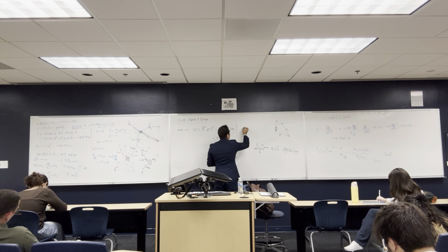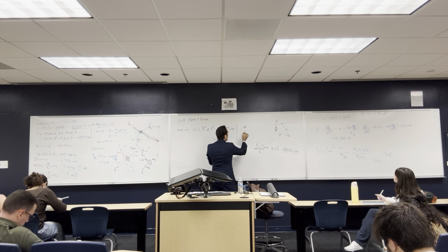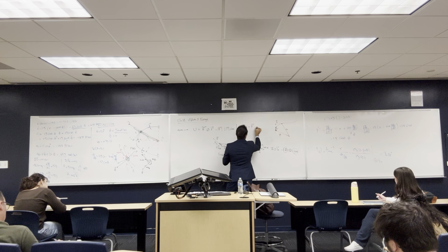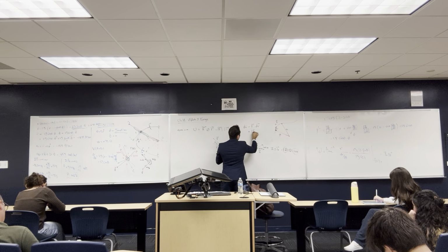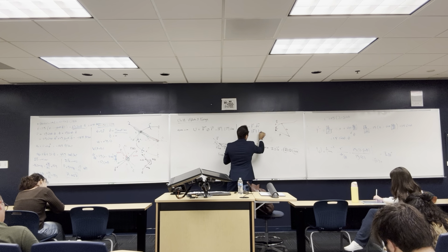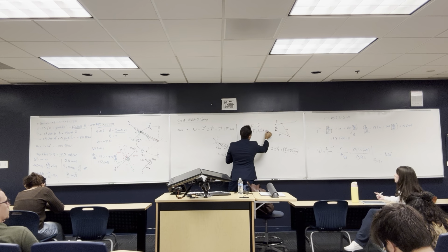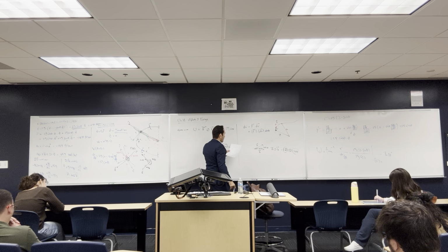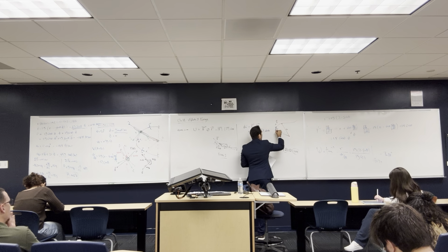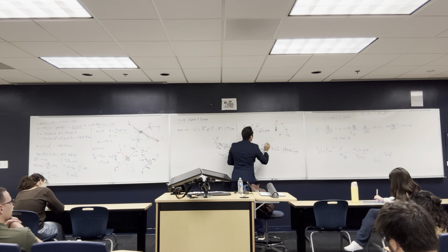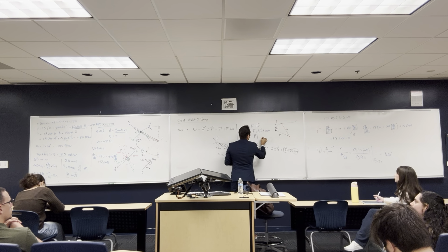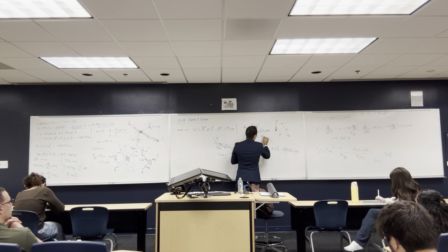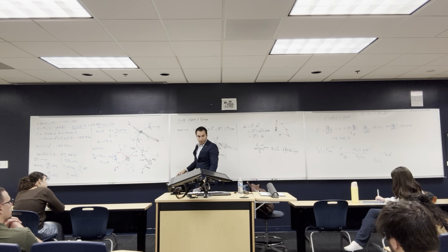So we say the infinitesimal work exerted, dU, is equal to the force F multiplied by the dr vector. If you want to find the magnitude, it's the magnitude of F multiplied by the magnitude of dr multiplied by the cosine of theta between the two vectors, and the magnitude of dr is ds, the distance traveled from here to here. So this is basically F multiplied by ds, and let's remove the vectors.